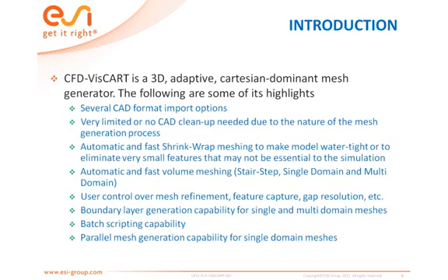CFD-VisCART is used to mesh three-dimensional geometries. It generates meshes that can capture the geometry curvatures and features. These meshes have a high percentage of Cartesian cells. Geometries can be imported in one of many supported formats.